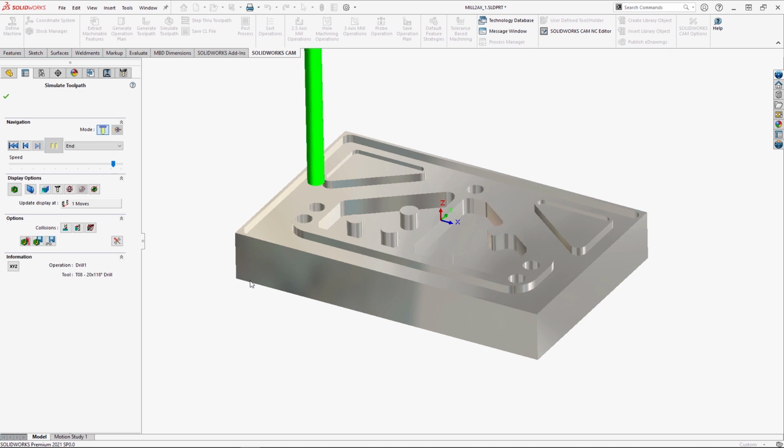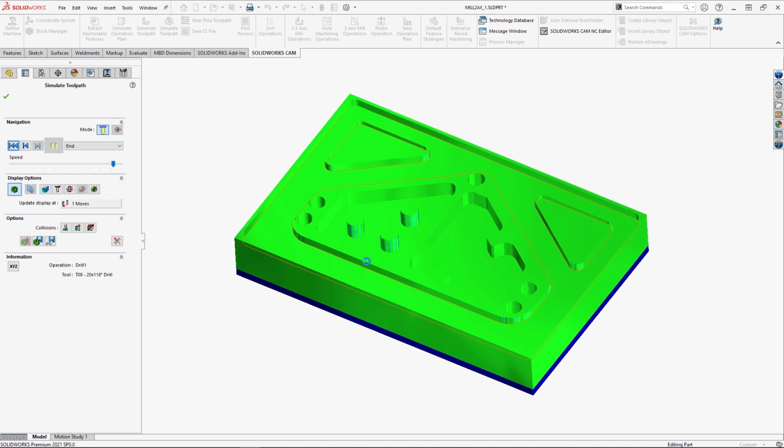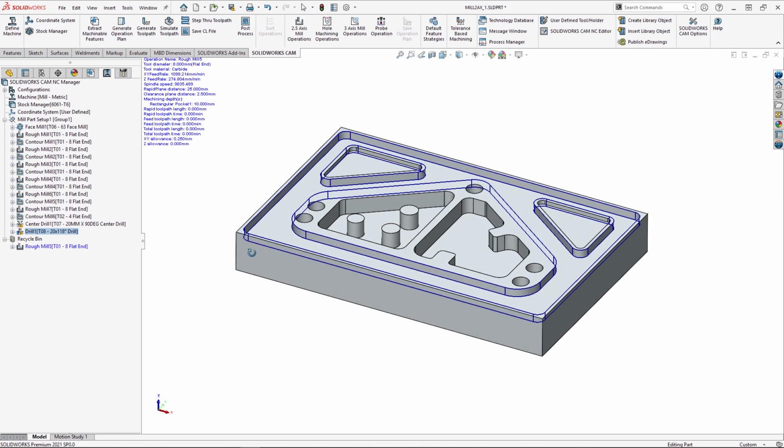And you can see here, the drilling finishes the job off. So if I click the button Show Difference, we can see here we have machined that part in its entirety. There's just a few tweaks that need to be done. The first for the depth on the outside, and the second to stop the spare machining on top, because that's not what we need in this application.